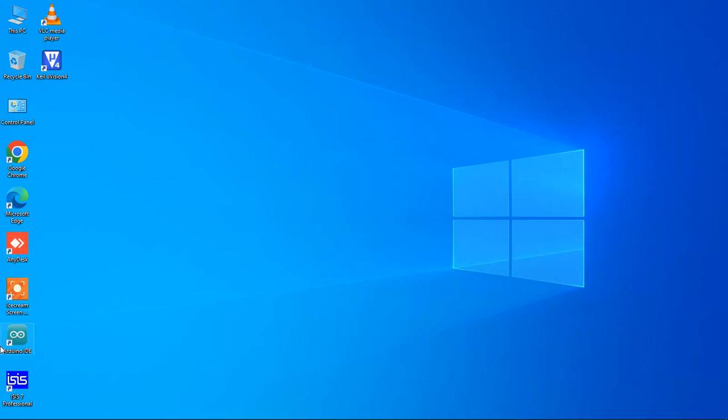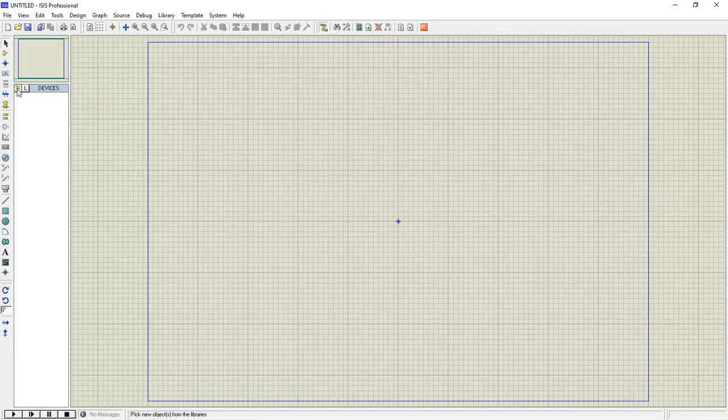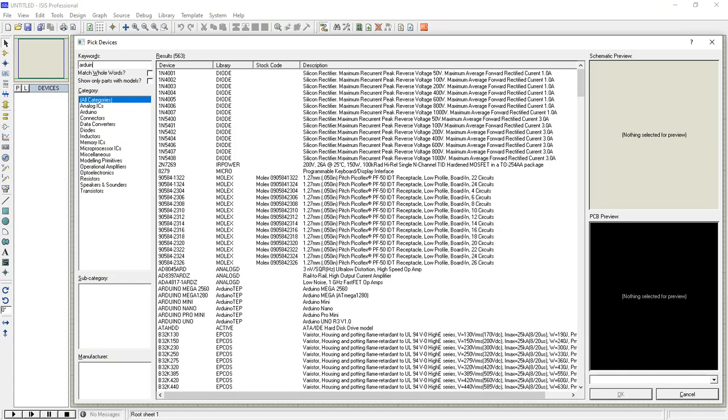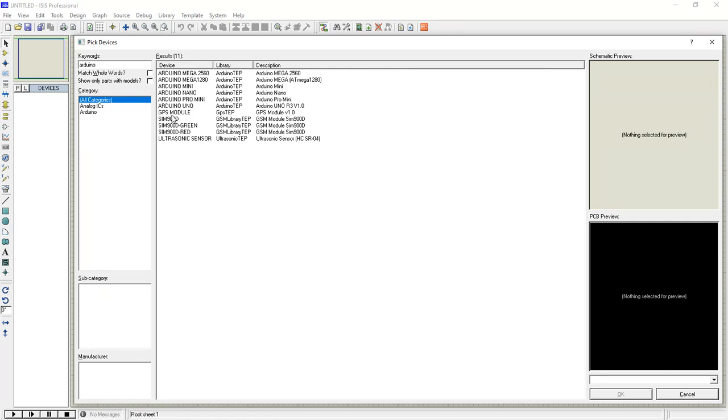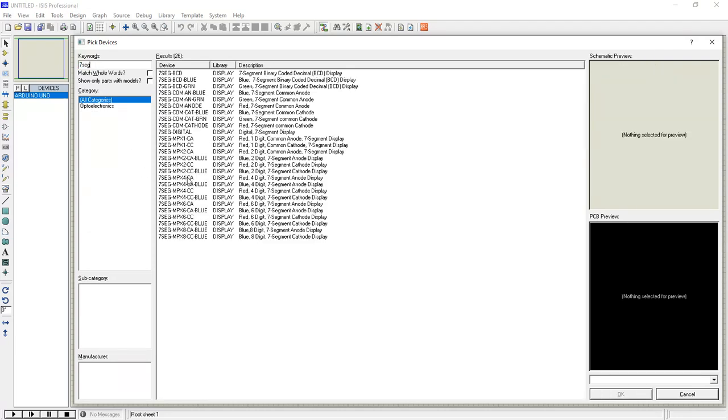All 7 segment digits' data lines are common as A, B, C, D, E, F, G, and H. Data lines are common, and you need to manage the common pins. Maybe it is a common anode or common cathode, so you need to manage it with programming. So that is the concept behind handling multiple 7 segments. Anyway, each segment has 8 data lines.